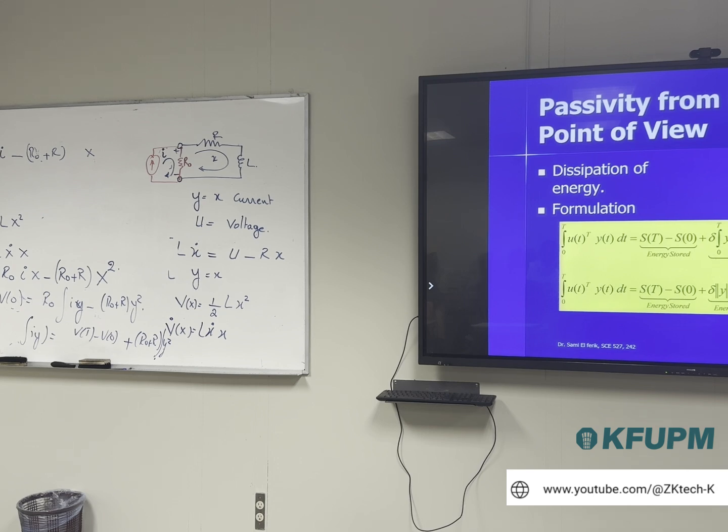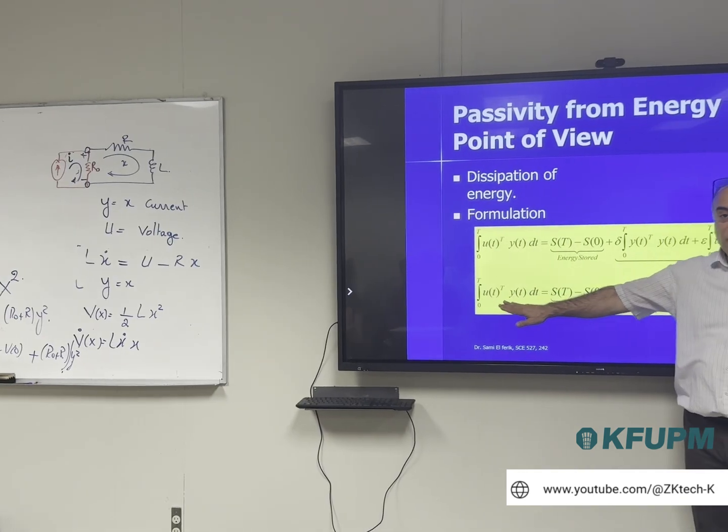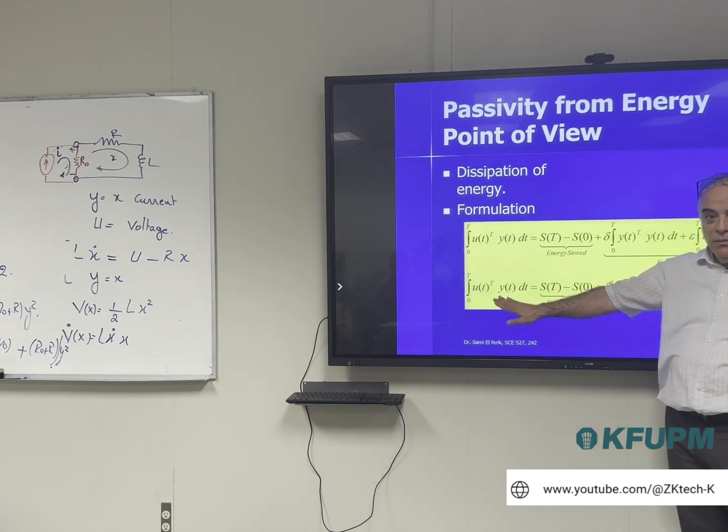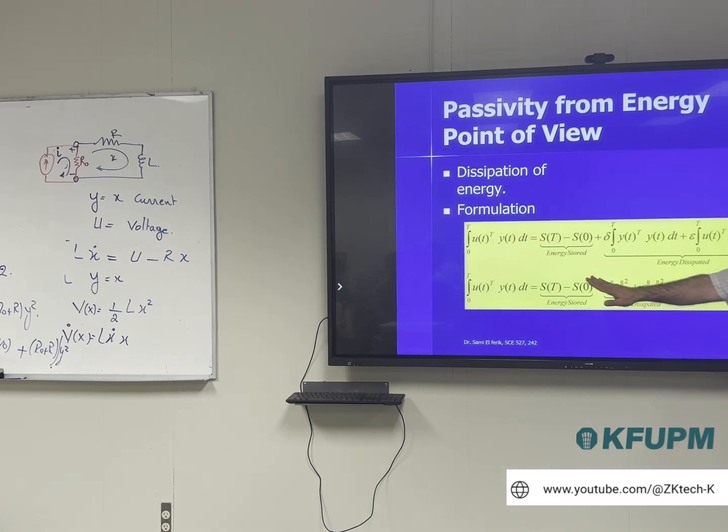So these terms, basically, this is what they are telling us. They are telling if there is any energy in the system, is energy coming from the supply. There is nothing produced in the system, and this is the definition of a passive system. A passive system does not produce energy. And if we'd like to look at where the input energy is going, we are going to say that it goes to either store or dissipate at the level of the input or the level of the output. Sometimes there are other terms that we can put across between the input and the other states. For example, if there are state variables, we can have internal dissipation of energy based on the states, depending on the state of the system. So, we are not seeing that.